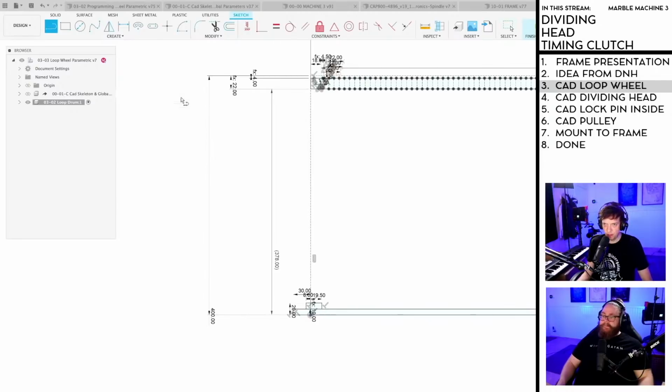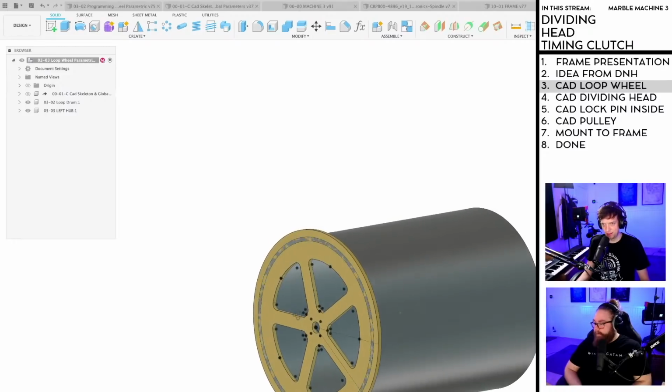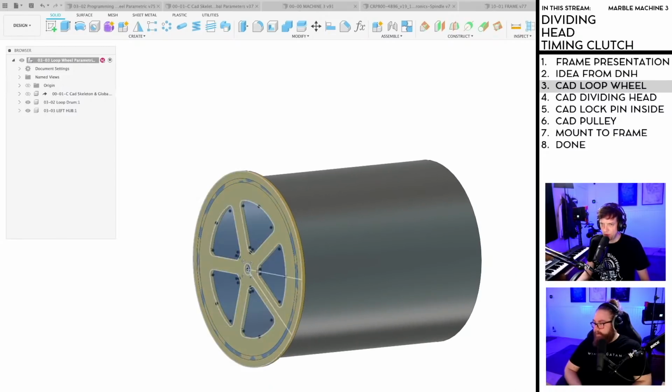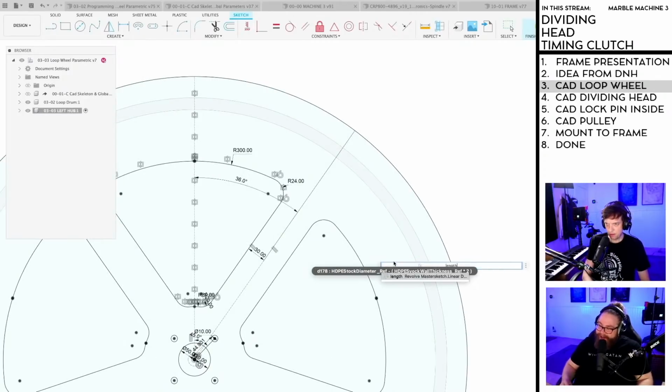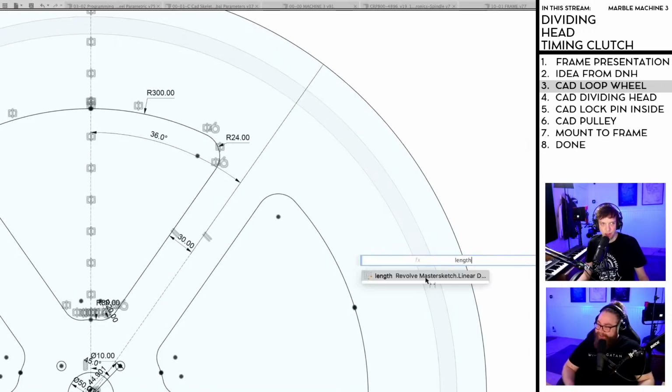I wonder if it's in the same sketch though. I'm just going to try this. So I go like this, and I say length equals 378. Now I created this parameter on the fly. I did this in this sketch. This is a little stupid, but we don't talk about that. Don't tell anyone about this, okay? So look, now I can just hit length.